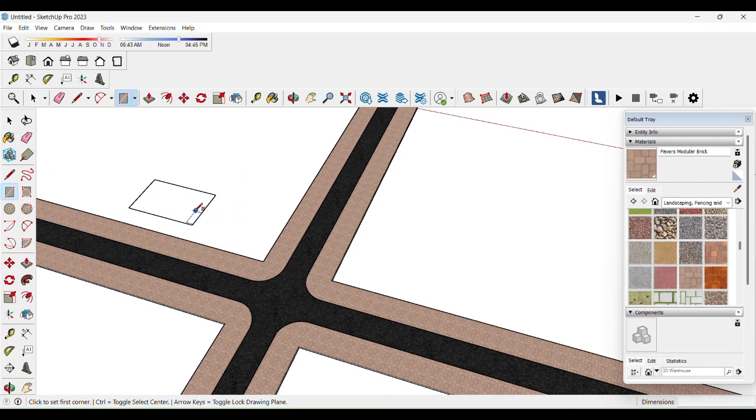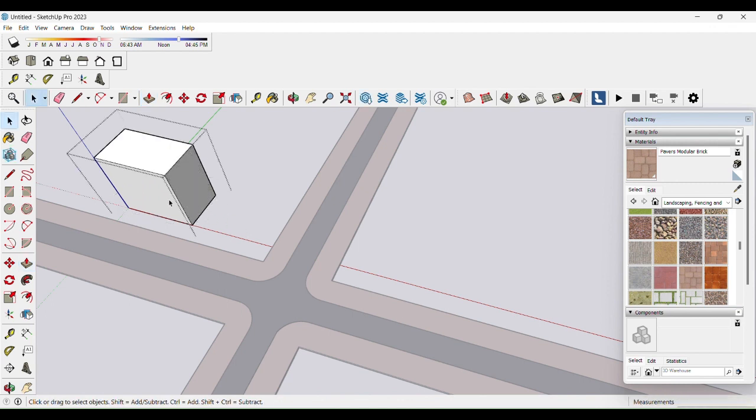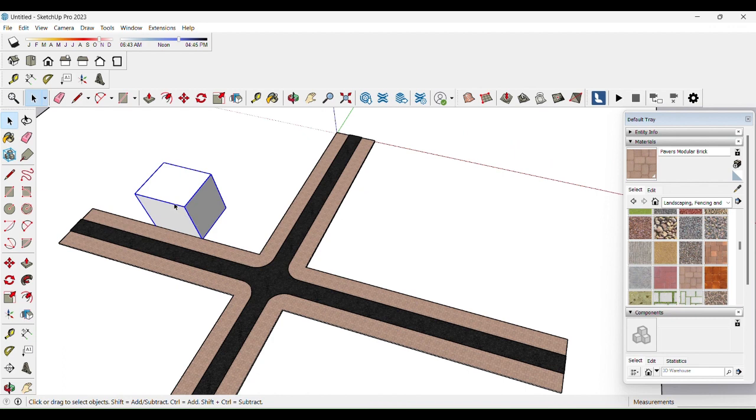Now as it's a street rendering, we'll create some context building blocks in the form of massing. Go to the rectangle tool and then push, create everything in maybe 1 or 2 stories and maybe a few blocks in a tall structure.